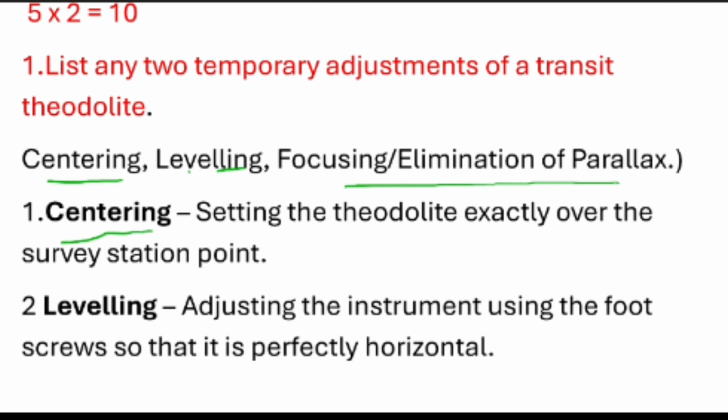Centering is nothing but you have to keep the theodolite exactly over the station point. That is what we call centering. Coming to the leveling, we have to adjust the instrument exactly in the horizontal position with the help of foot screws.